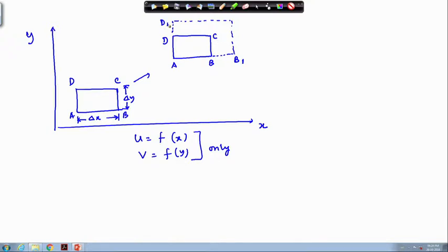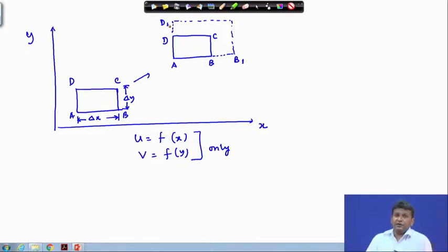Because you cannot have simultaneous extension of both the lines AB and AD. In order to preserve continuity, if one line expands, the other line should shrink in size if you are considering a 2D element. Of course, this is possible if you have a third dimension, at the cost of a reduction in the thickness of the fluid element. If you highlight these things, they become more understandable and clear to the students.